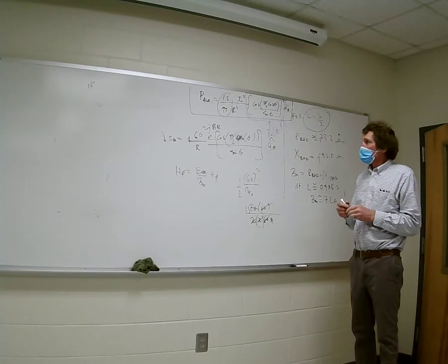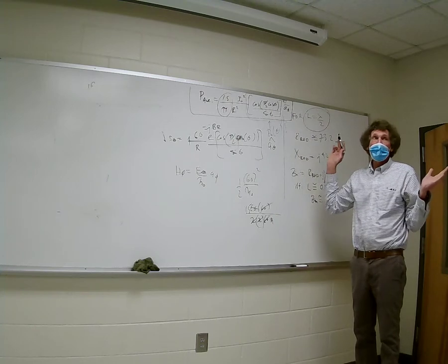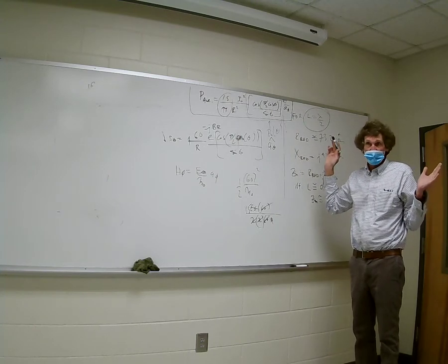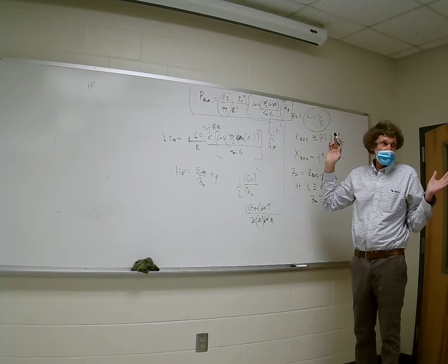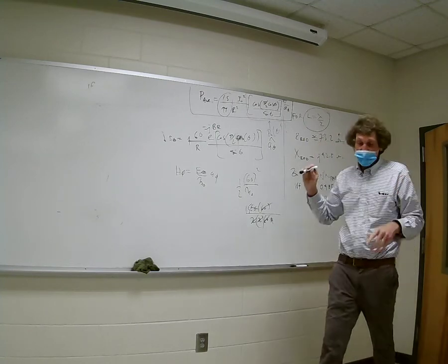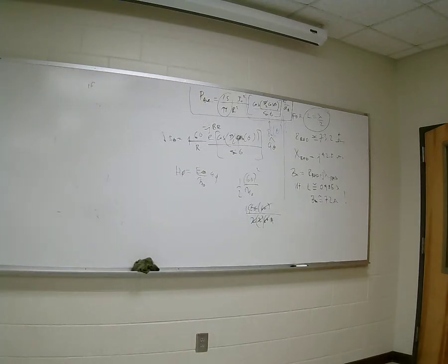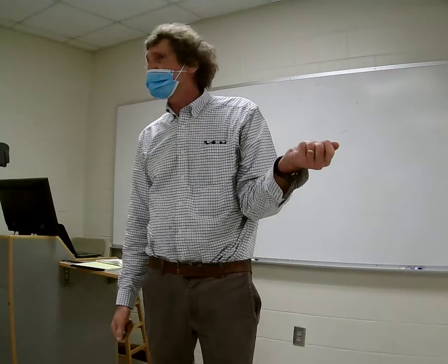The power radiated is there. If you've got the E field, you've got the power radiated. Just take the magnitude of the E field and square it. If you want the average power density at the point, once you have that, multiply by one half and divide by eta. But I never do that. You know what I do? The only thing I worry about with antennas is the radiation resistance and the gain.